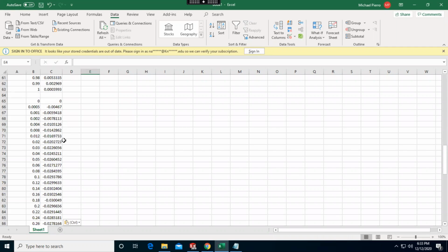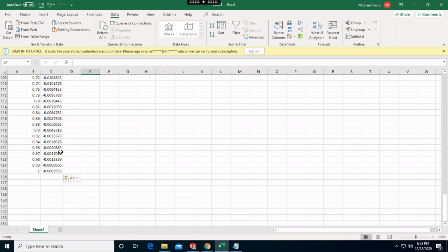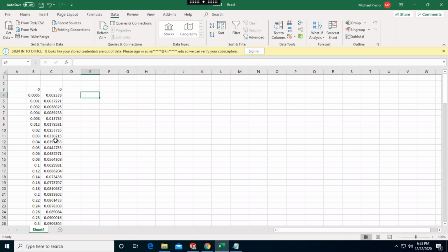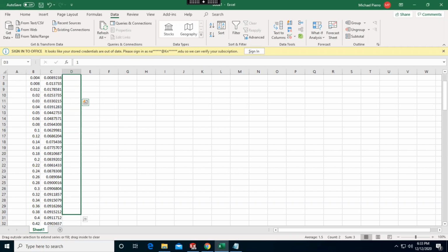And as you can see, it separated them into columns already. If not, you will need to separate them into separate columns using Excel. And what we need to do to make this compatible for SolidWorks is we need to flip these coordinates right here. And the easiest way to do that is to actually number all of these lines right here down to where we're going to be flipping it.